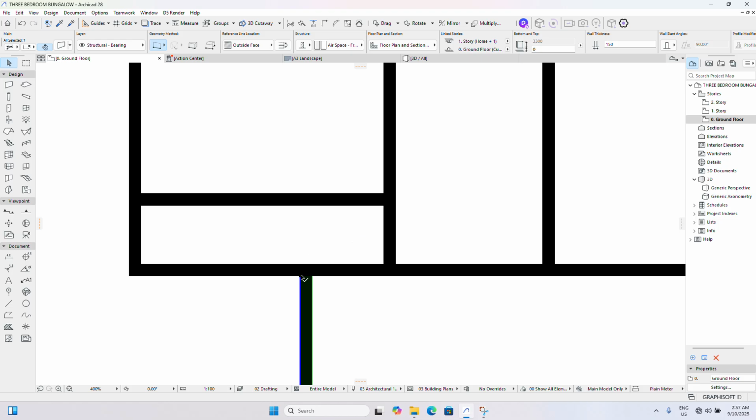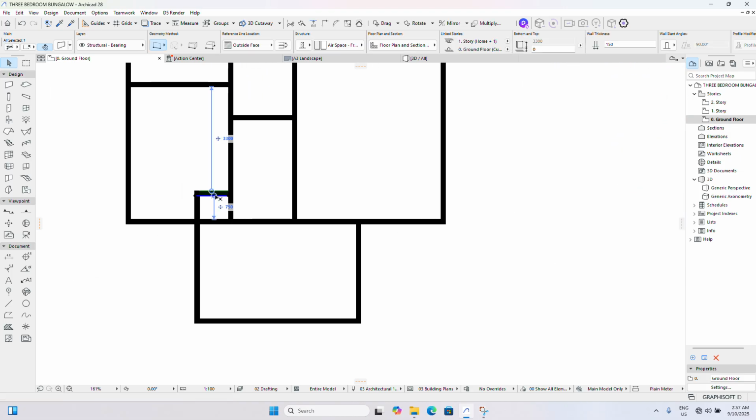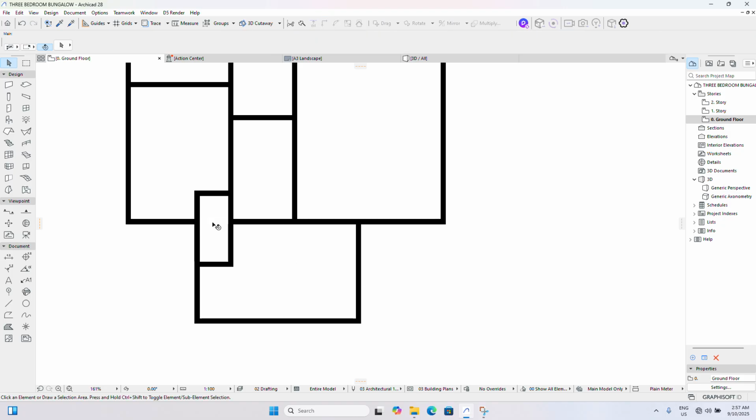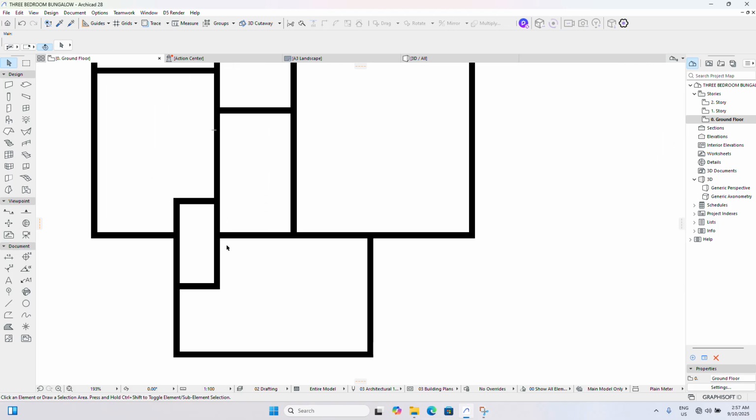Remember when I said if I want to drag this up, once my mouse mark is good, it means I'm dragging an object. I'll click on it, make sure that it's on this stretch, stretch it, and hold my Control key to cut it here. Now with Ctrl Shift D, I will bring it down. I can choose 2.1, which is 2250. If I choose that dimension, I will join it together, and I will also open here so that my door will come inside the toilet in here.